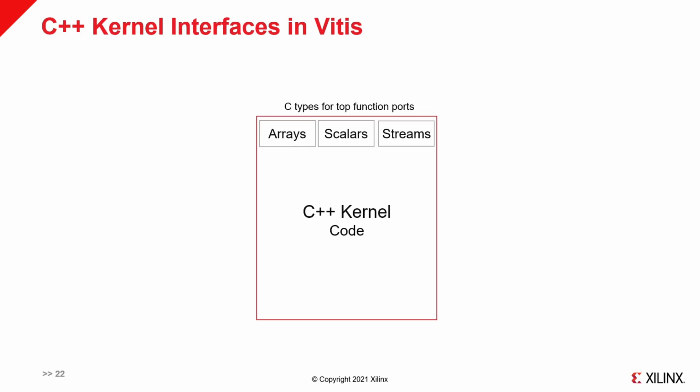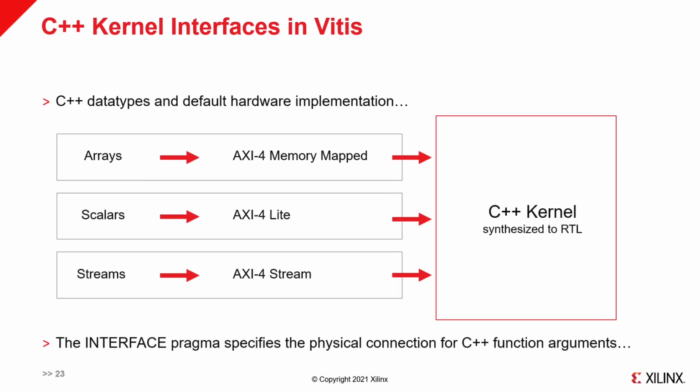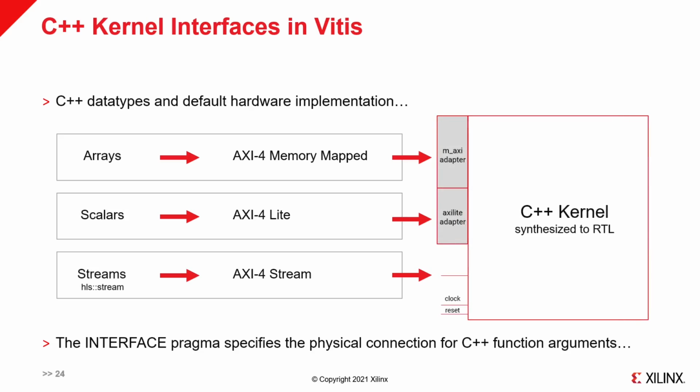So overall, once v++ compiles our C code, it looks at the ports of the function to accelerate, and in conjunction with the interface directive, it connects the post-C synthesis synthesized RTL from the kernel to AXI4 connectivity blocks that are automatically added by the tool and that you may configure through the interface directive. The one level of detail down that I want to show you on this slide is that actual adapters are inserted to embody this connectivity at a low level.